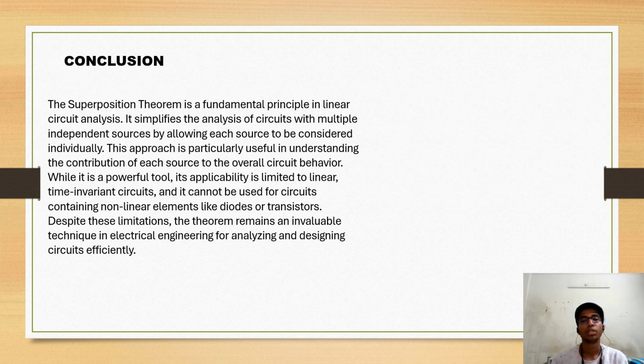Conclusion. The superposition theorem is a fundamental principle in linear circuit analysis. It simplifies the analysis of circuits with multiple independent sources by allowing each source to be considered individually. This approach is particularly useful in understanding the contribution of each source to overall circuit behavior. While it is a powerful tool, its applicability is limited to linear time invariant circuits, and it cannot be used for circuits containing non-linear elements like diodes and transistors. Despite these limitations, the theorem remains an invaluable technique in electrical engineering for analyzing and designing circuits efficiently.